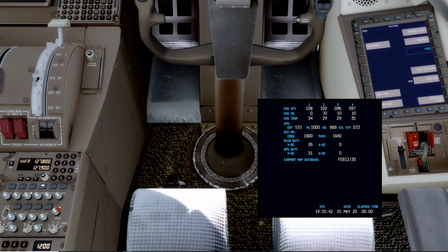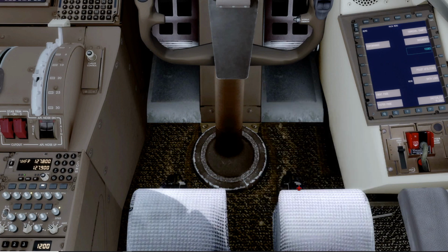And so you hear the hiss. If you're going to do that, but virtually, I don't know how you do it. You don't have enough hands to do it in the virtual simulator. But the Boeing procedure is just to push that down, push that. It's continuous, hold it for 10 seconds, and make sure you don't get a drop here by more than 100 psi. And that's the oxygen check.